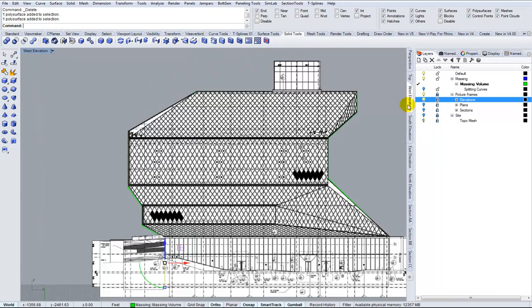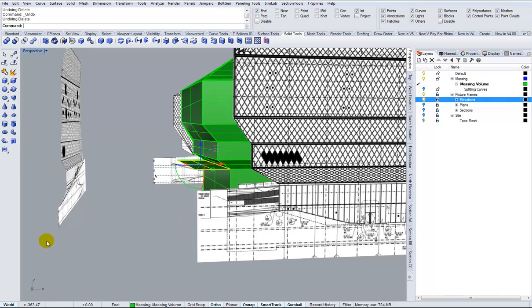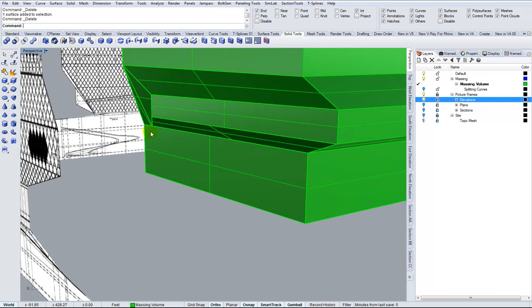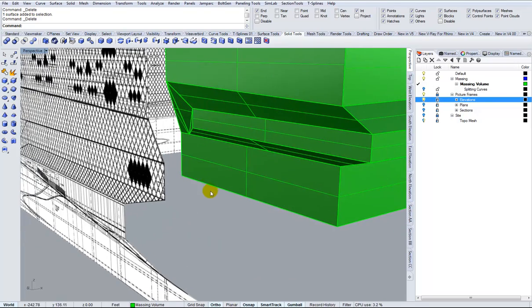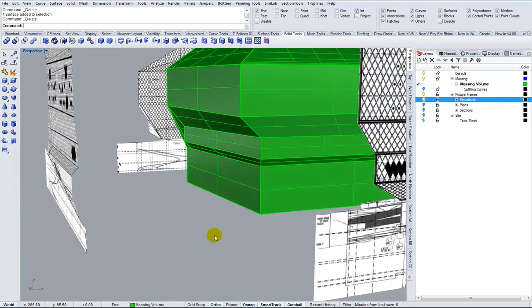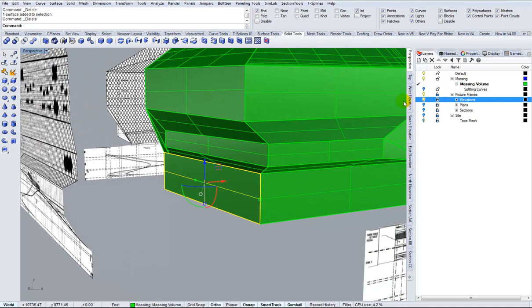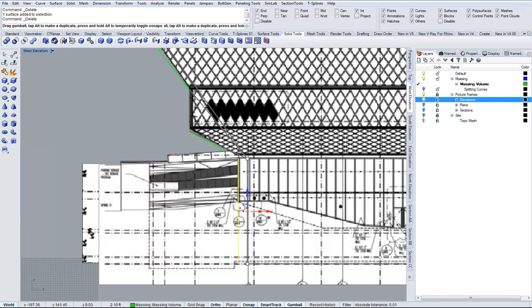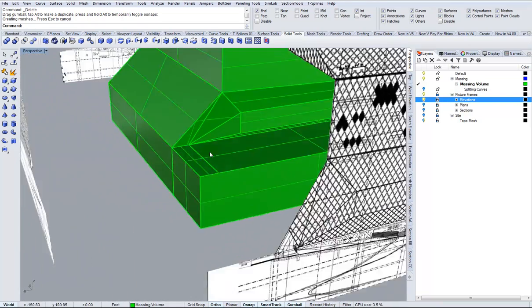So go back to, I believe it's the west elevation, and hold down control. Start dragging it out first. And I think what actually happened is when I moved it, I grabbed this little extra edge here as well. I'm glad that came up, because once you get a little bit of extra geometry like we've got, it's a little tougher to grab things in elevation. You want to start grabbing things only in perspective, so you know what you're grabbing. So I'll do my control shift and make sure I'm only doing that face now, and going back into the west elevation and starting to drag it out, and then hitting control to make it an actual extrusion, so that I'm not bringing out too many objects. So that looks way better.